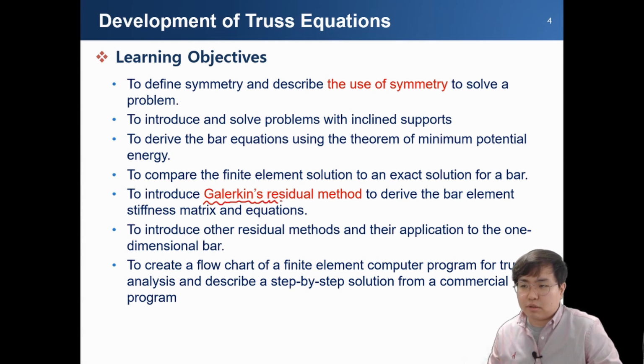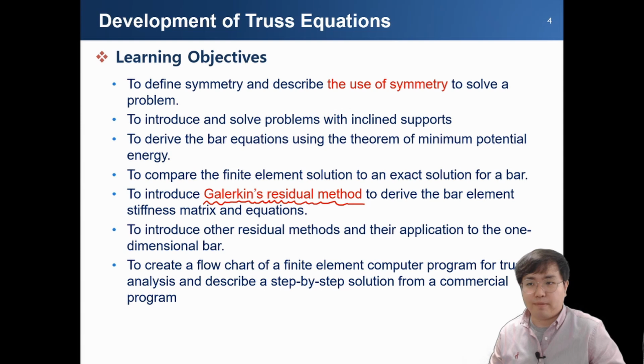Please also remember another method to derive this finite element equation, the Galerkin residual method. This is another numerical method to derive the discretized equation for the FEM solution in matrix form. Compared to the energy method, the Galerkin residual method uses the differential equation itself, in a very similar form. At first it is harder to understand the Galerkin residual method directly, but once you understand how to use it, you can easily discretize any partial differential equation. So I like those methods, and I'm going to introduce them to you.